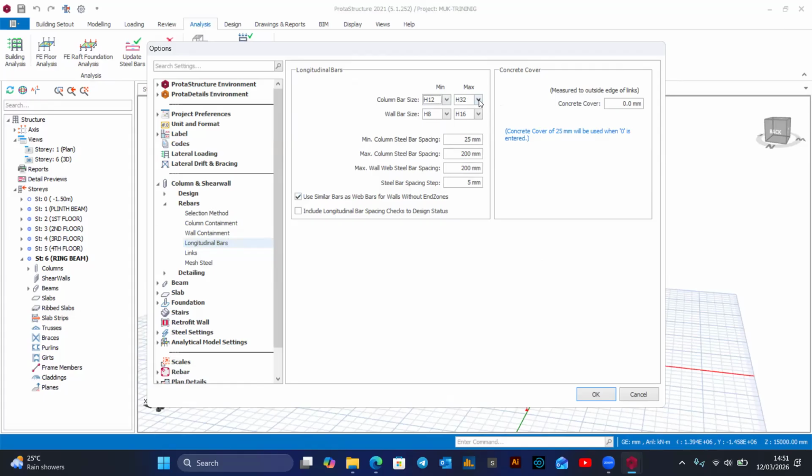When you are designing a structure, we are looking at the cost effectiveness of the project. So when we are making judgment, it's either area of concrete or number of reinforcements that you're going to have in a section. On the market, steel is more expensive compared to concrete. So even here, the higher the size, the cost will be increasing. Now, let's have this limited to 20. The maximum is going to be 20.